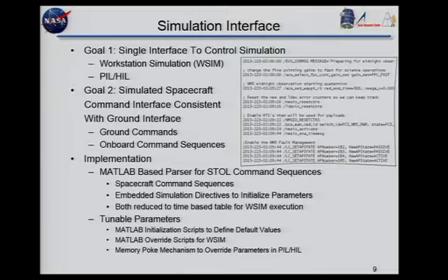There were two types of script, one that would represent commands from the ground, and the other one that would represent uploaded command sequences. And again, we parsed those in, and we reduced them into time tag tables inside the Simulink environment. These were elements that would be strictly for the workstation sim, but allowed that to operate like our other products and like the real spacecraft.